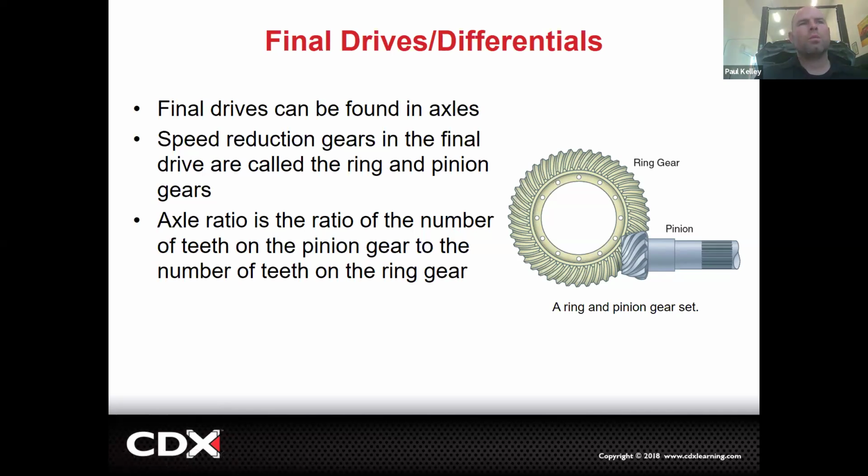The reason for that, if you paid attention to the assignment, which was the video and discussion, when we bring this pinion in at this angle, we could actually use a little bit more simplified gears, but we needed to drop this pinion down and we needed to get it to engage, not at a 90 degree, like it's coming in sort of more towards the bottom. So there's a lot of this wiping action on these gears. And so they're hypoid mainly because it's not coming in at a 90.